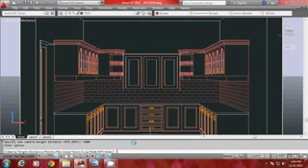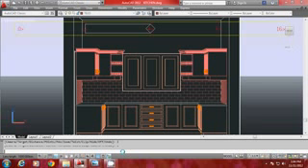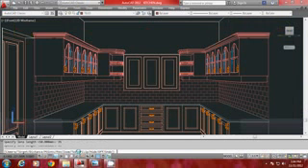Or else if you want, you can change the focal length of the camera by using the zoom option. So type Z for zoom. Now it will show you the current focal length of the camera as 50 mm because that is a default focal length. I would like to bring it down to say 35 mm. You know that when you reduce the focal length of the camera, the field of view of the camera will get widened. So it will become a wide angle view.